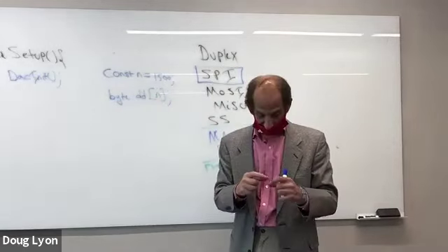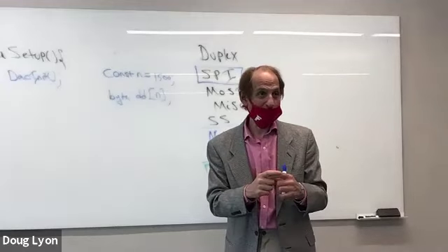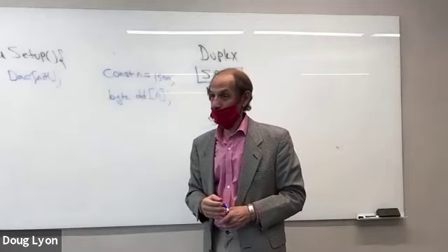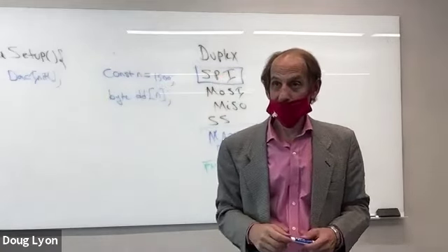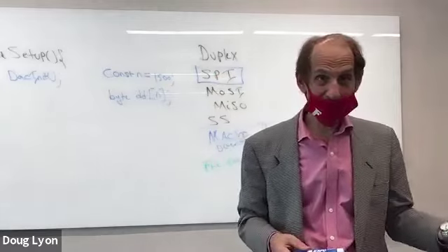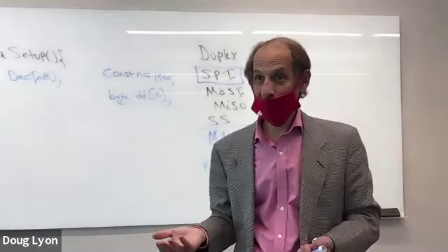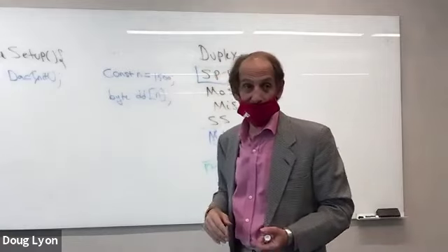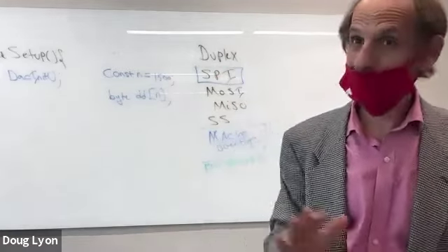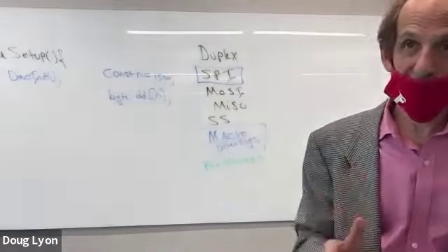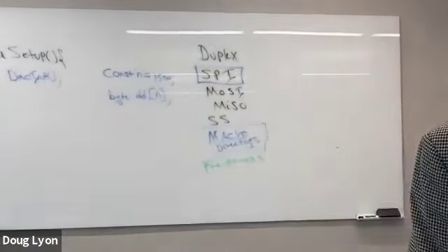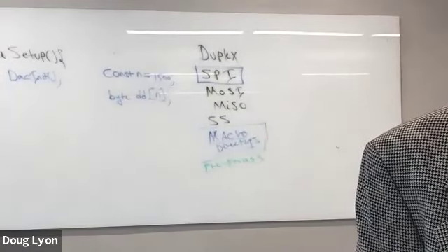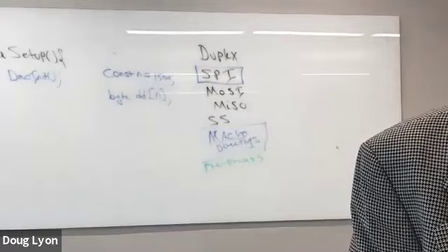Why? Because it's a little tiny 8-bit toaster controller, that's why. It's got 2K of RAM. You try and go beyond 1500 bytes, and you're not going to have enough room to breathe. 2K of RAM is like 2048, and there's going to be room for scratch memory, too. So after 1500 bytes, you're done. That's it. Arduino's finished. So this is an Arduino problem, right? This is not a C problem, but it is a practical problem. When you have finite hardware, you can't just keep going. And that is the answer to question number 1 in homework number 3.